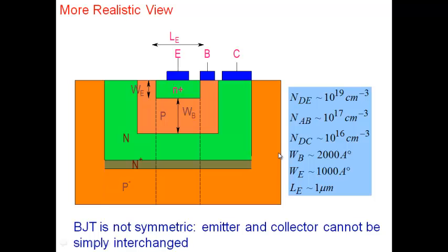So what you end up getting is an NPN. You get 2 PN junctions, and both the junctions are kept reverse biased. So the 2 transistors that you see here are isolated from each other by 2 reverse bias junctions. And we know reverse bias junctions are non-conducting. Okay, so I'll show you a picture maybe next time, which will clarify it a little bit more.